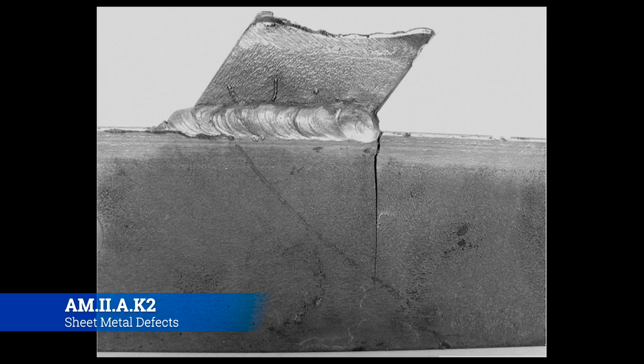If you remember back in general, I told a story about finding a crack in the tail rotor gearbox mounts on the OH-58 one day in Baghdad. It's just kind of a process. We'd always grab the tail rotor gearbox drive shaft and lift up on it, because if anything was cracked, it would move. I picked up on this one, and it moved a pretty good distance. So this is something you want to pay attention to. This is also what a lot of your NDI inspections are going to come looking for. They're looking for cracks inside of metal, just because over time the stress and strain of flight will weigh on them, and the cracks will start to form.